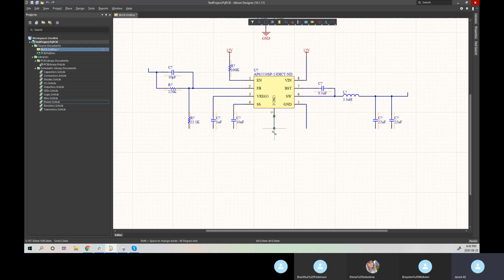But there's nothing wrong with bringing everything to a central point, so that all of your components are just sharing a single ground port. And the connection, electrically, is identical between this and the previous, where we have a ground point on each. It's purely just preference and how you want to make it look.